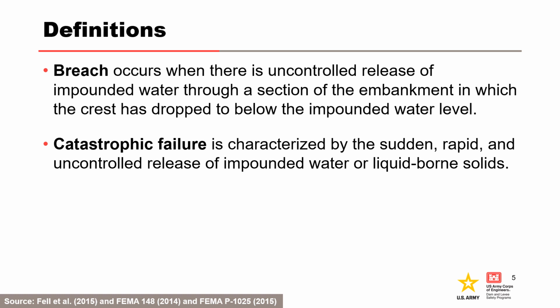Fell et al. 2015 and ICOLD Bulletin 164 refer to this phase of internal erosion as both breach initiation and breach. Breach occurs when there is uncontrolled release of impounded water through a section of the embankment in which the crest is dropped to below the impounded water level.